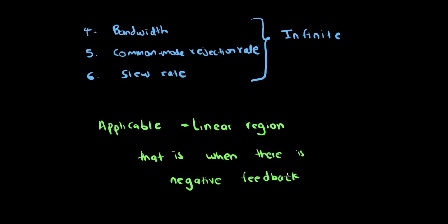That is, when there is negative feedback present, right? And the output is not stuck at its positive or negative supply rails.